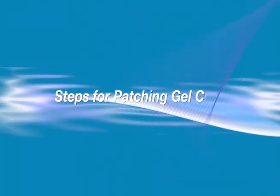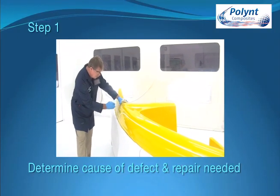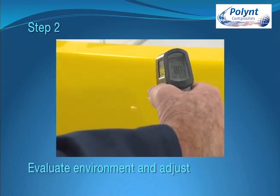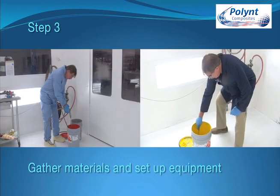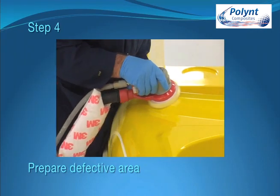Now let's review the steps for patching gel coat. Step 1. Determine the cause of the defect and determine the type and extent of the repair needed. Step 2. Evaluate the environment and adjust as necessary. Step 3. Gather the materials and set up the equipment. Step 4. Prepare the defective area.